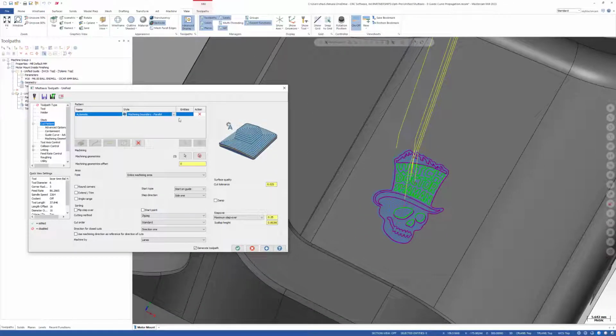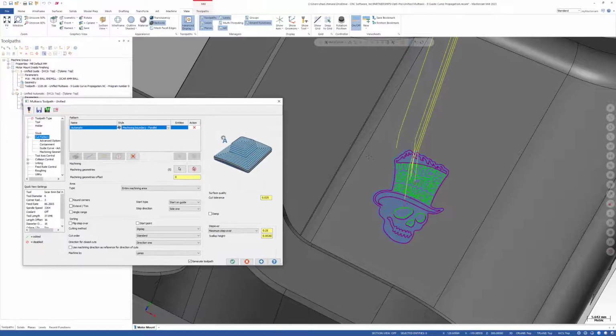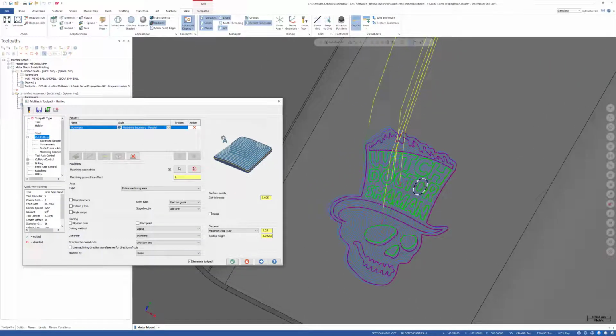So machining boundary takes into account any containments or avoidance regions or anything like that, and creates Stepovers based on that. So essentially, you'll see this toolpath is almost the same as the one before, right? We could do this in that first toolpath because it's using this to create the motion. It's just propagating inward instead of outward.